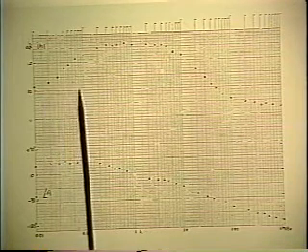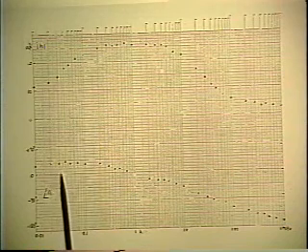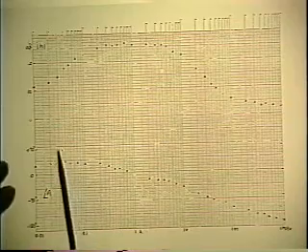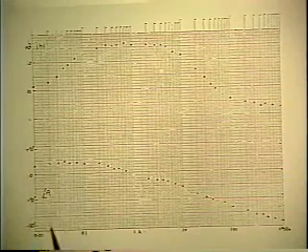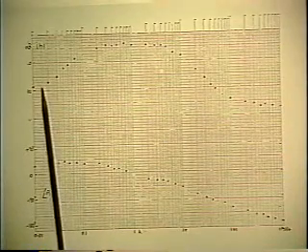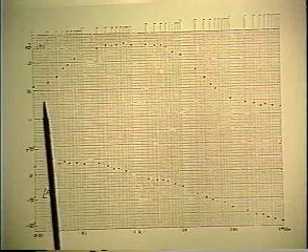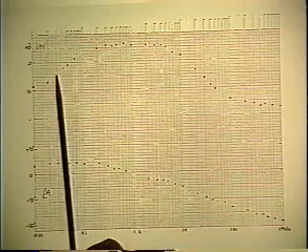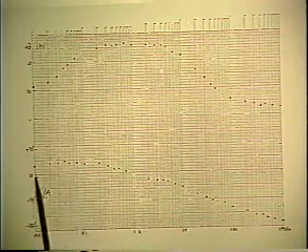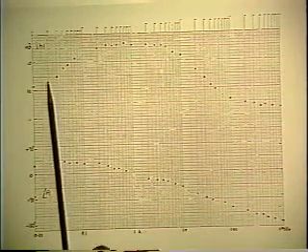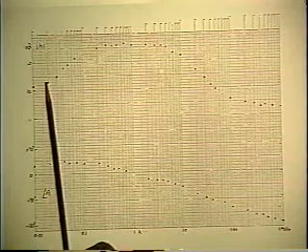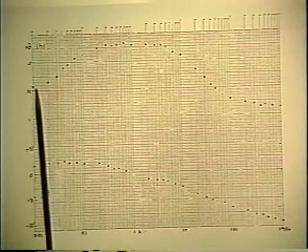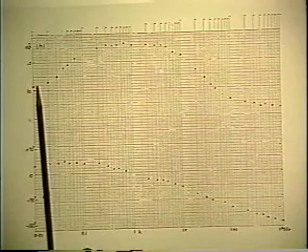This means it's time to go over to the phase data and see if you can get a better idea, bearing in mind what we talked about already, that the influence of this corner, if it exists, will extend much further away from it in the phase data than it will in the magnitude data, namely a decade in phase and only an octave in magnitude. So we should use the phase data to get a better fix on the position of this zero, if there is one.